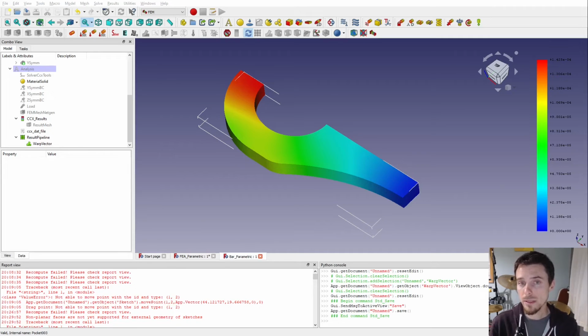we are doing this is just by, say, picking the maximum von Mises stress and the maximum displacement. Again, this is just an example. Then you can change the script to extract whatever parameters you want. You can extract the probability distribution of stress. You can get the principal stresses. If you're dealing with different materials, you can get the Tresca stress, or you can get deformations, or whatever you need to get out.